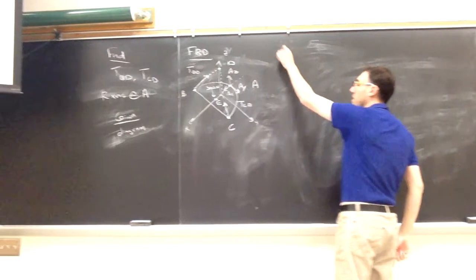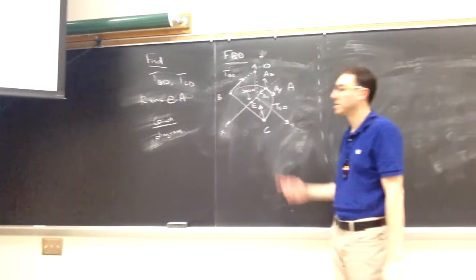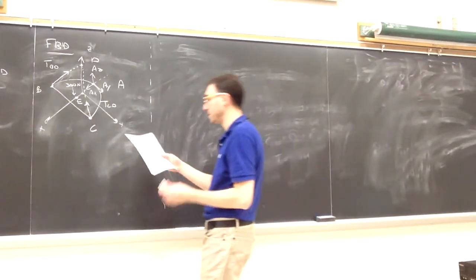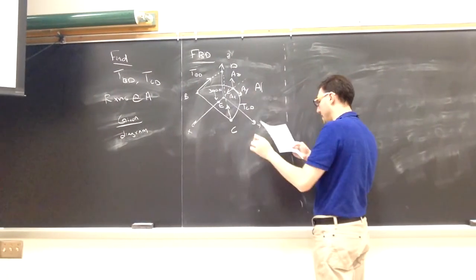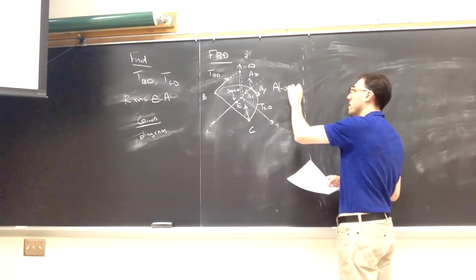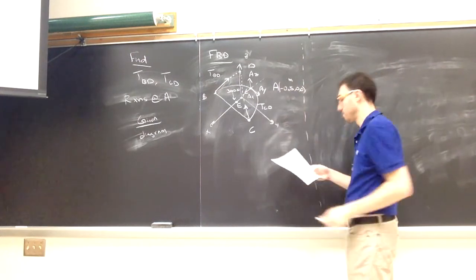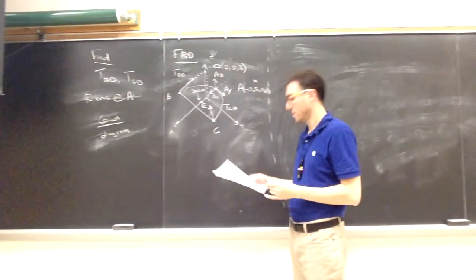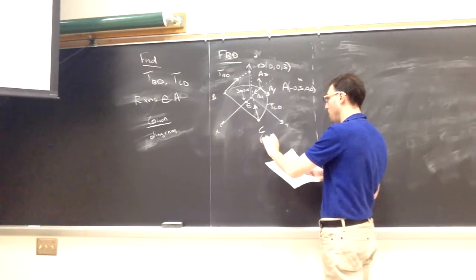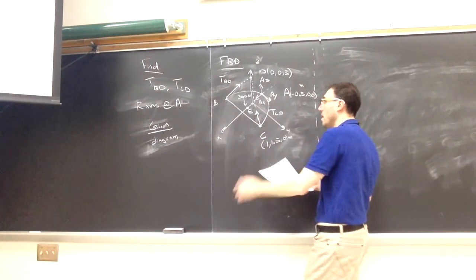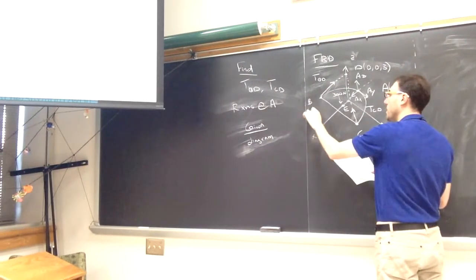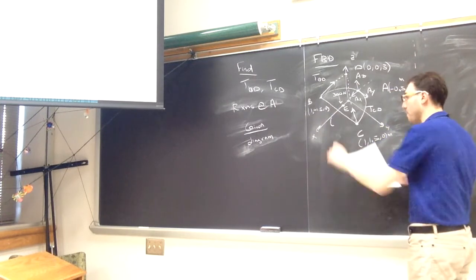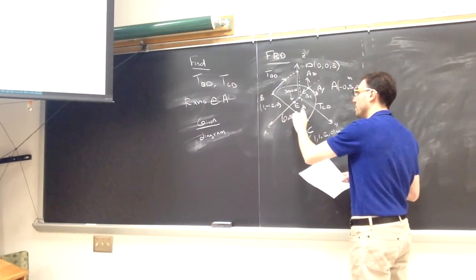The last thing we need then on our free body diagram are coordinates. They'll make the writing of equations easier. Based on where our coordinate system has its origin, we'll have A at negative 0.5, 0, 0. All of these will be in meters. D we need because that's where the ropes terminate at 0, 0, 3. C is going to be located at 1, 1.5, 0. And B at 1, negative 1.5, 0. And this point E that I added will be at 0.5, 0, 0.